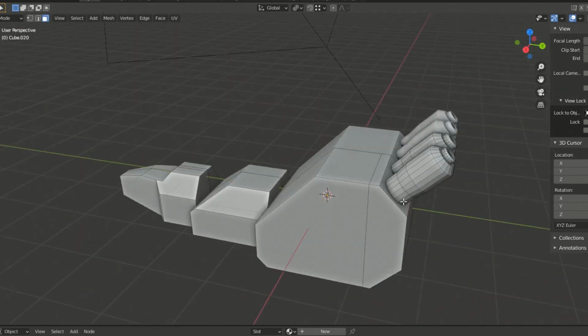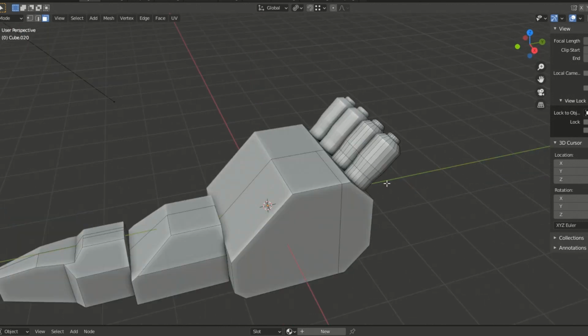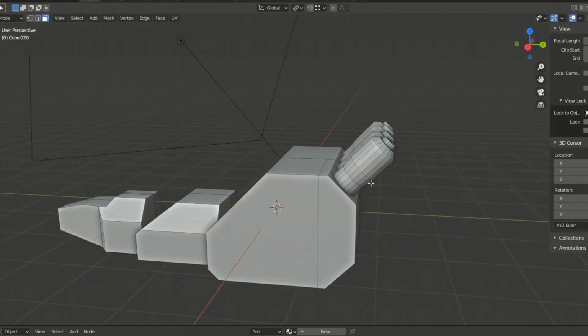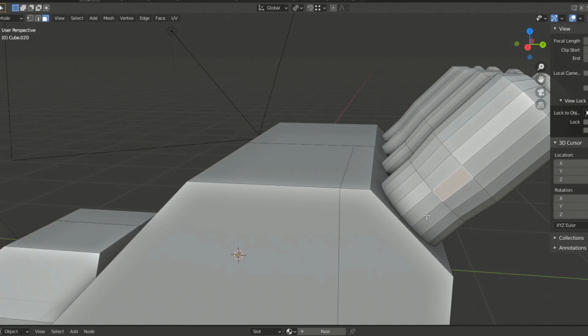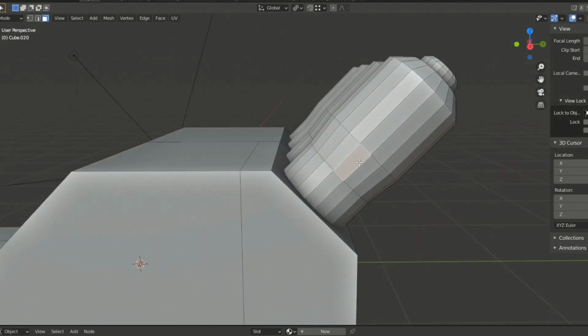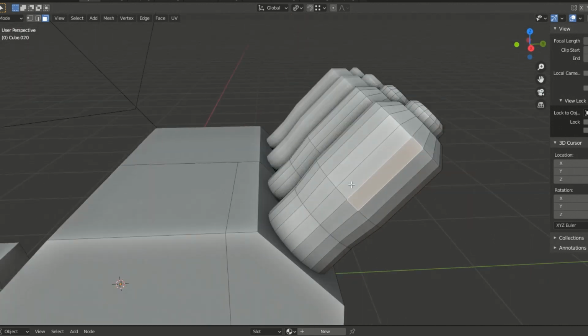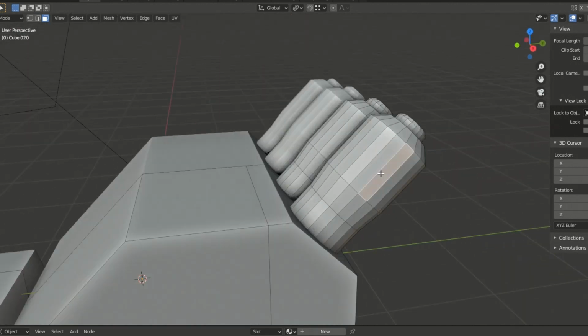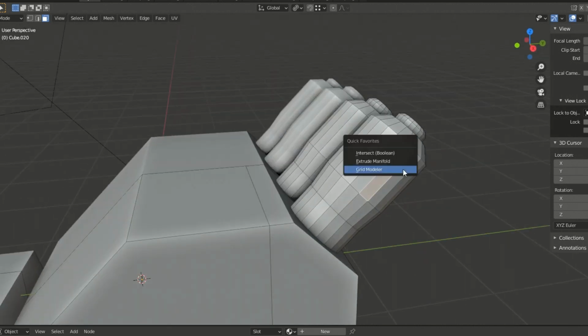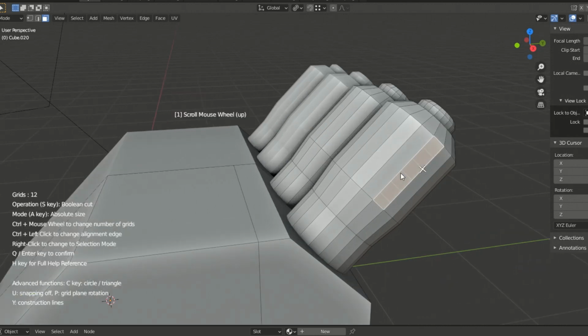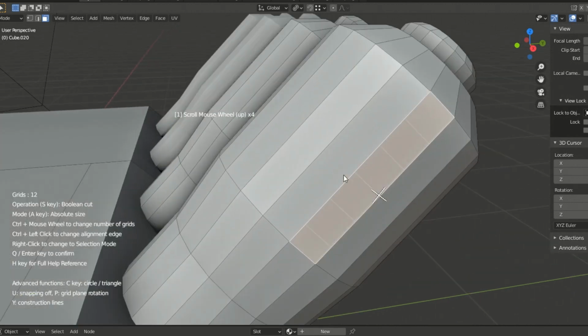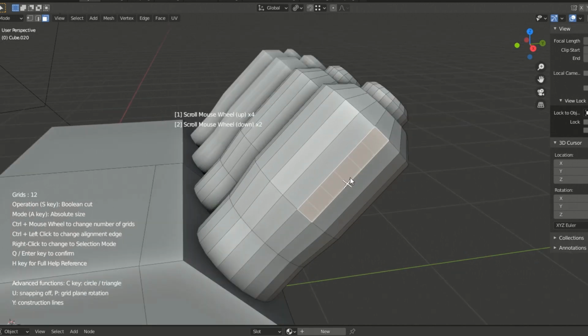But if we want to add a wing on the burner, I can select the face and then create a wing. I will show you how to do that. Let's say I want to create a little wing on here. So I select this face and then run Grid Modeler. You will see that a very small grid shows on this face. We don't have to worry.